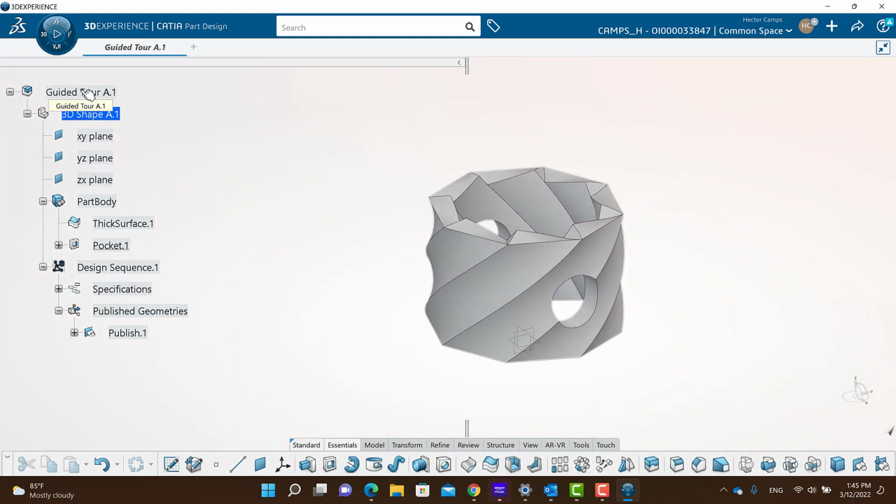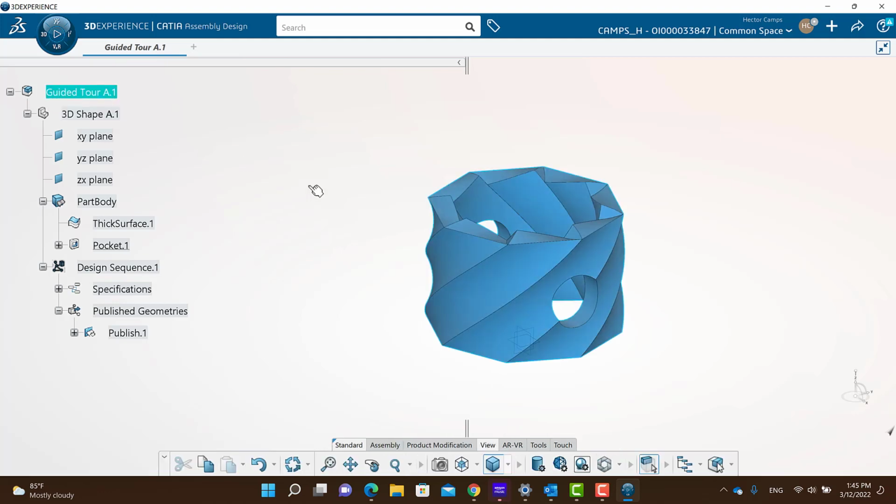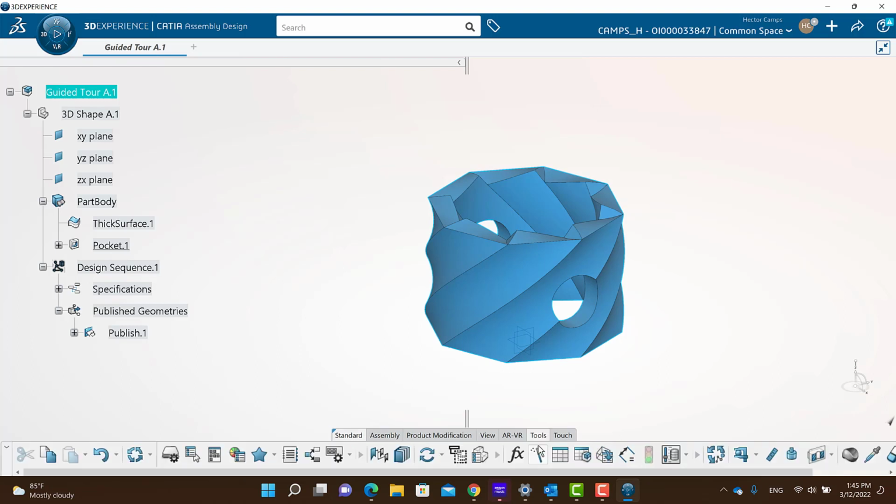To explore the solid geometry aspects of the model even further, if you click at the top of the tree and you come down to tools, you're going to find a clipping tool. Notice that when I do that, this switches to assembly design. So this icon here is an assembly, right? It's a collection of parts and shapefiles put together that makes an assembly.